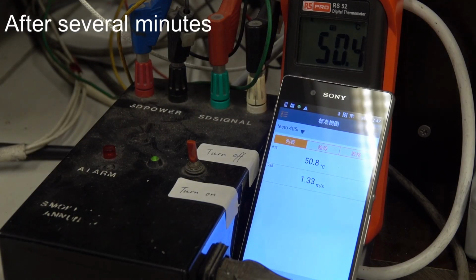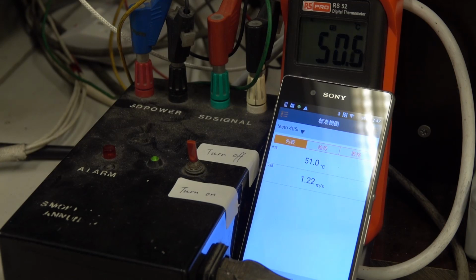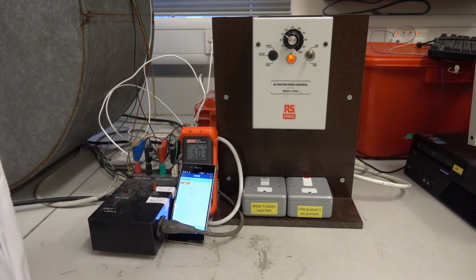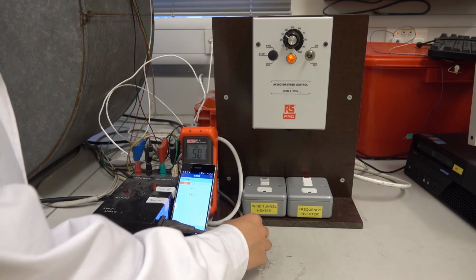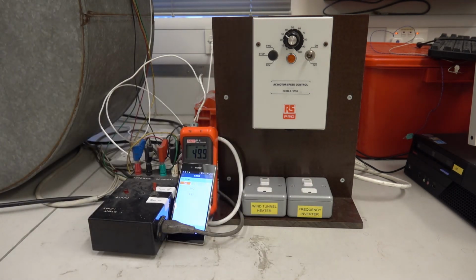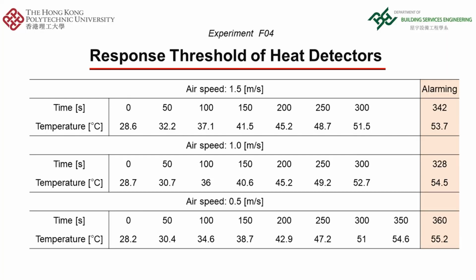Several minutes later, when the alarm is ringing, stop recording the time. Turn off the alarm and the heater. Wait for the wind tunnel to cool down to room temperature, and then we can start another group of tests. Totally, 3 wind speeds were tested, and all data are summarized here. Please use those data to finish your logbook.